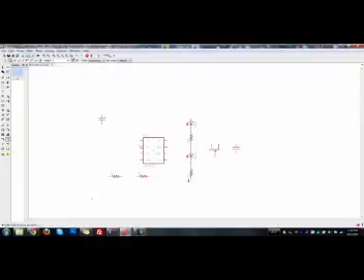Now, there needs to be ground here, and you can do ground in one of two ways. You can either just connect all the grounds in the circuit to each other, or you can add a special component that defines a ground and adds anything attached to that net or that signal layer as a ground. So let's go ahead and do that.